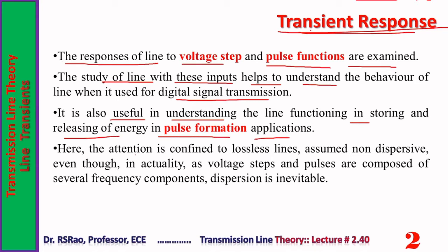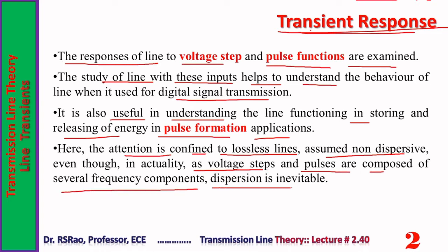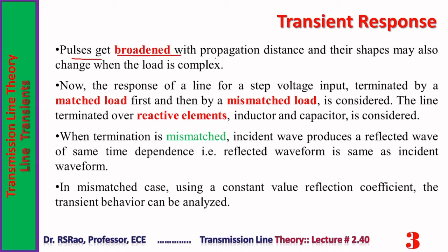In the present session, the attention is confined to lossless lines, which are assumed non-dispersive, even though in reality, as voltage steps and pulses are composed of several frequency components, dispersion takes place inevitably. So it is an assumption, somewhat unreal, that the lines are non-dispersive in the present discussion. Pulses get broadened with the propagation distance, and their shapes may also change when the load is complex.